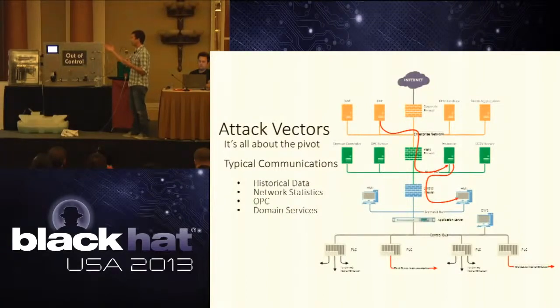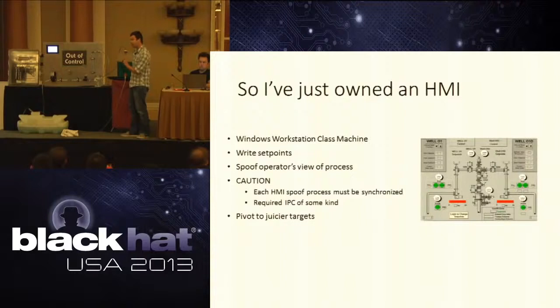One would be just regular old historical data, but what we're going to mention quickly here is OPC. If any of you have heard of OPC, it stands for OLE for process control, or object linking and embedding, for OLE. Essentially it rides on top of DCOM, which many of you might know is a deprecated protocol used by Microsoft, but it's used everywhere in the process control industry. The implication is that because it uses DCOM, you have to open up a ton of ports on your firewall to allow that data to traverse it, because it picks a port at random to assign to that OPC communication. So even though it's deprecated by Microsoft, you see it everywhere in the process control industry.